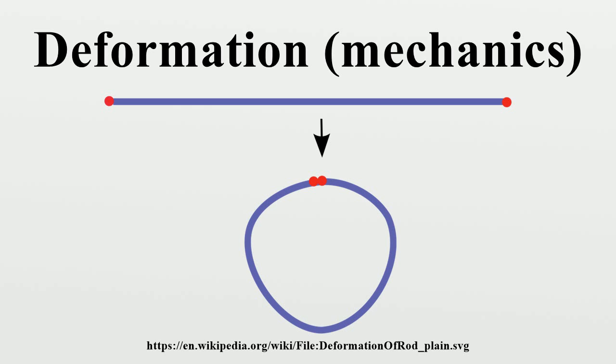Infinitesimal strain theory, also called small strain theory, small deformation theory, small displacement theory, or small displacement gradient theory, is where strains and rotations are both small. In this case, the undeformed and deformed configurations of the body can be assumed identical. The infinitesimal strain theory is used in the analysis of deformations of materials exhibiting elastic behavior, such as materials found in mechanical and civil engineering applications, e.g., concrete and steel.